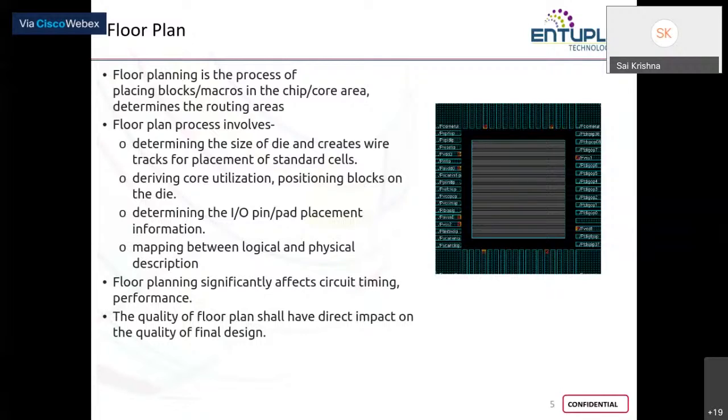In physical design, whenever it comes to timing, please do remember one thing, that longer the wires, higher is the resistance, and so higher will be the delay. Because of which the setup slack of a sequential cell can be adversely affected.